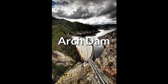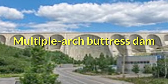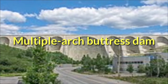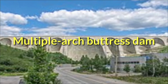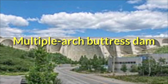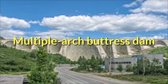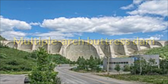Since they are thinner than other types of dams, they require much less construction material, making them economical and practical in the remote areas of any country. The multiple arch dam, on the other hand, consists of a number of single arch dams with concrete buttresses as supporting abutments. For example, Daniel Johnson Dam in Canada is the best multiple arch dam. Multiple arch dams do not require as many buttresses as hollow gravity types, but they require a good rock foundation because the buttress loads are very heavy.